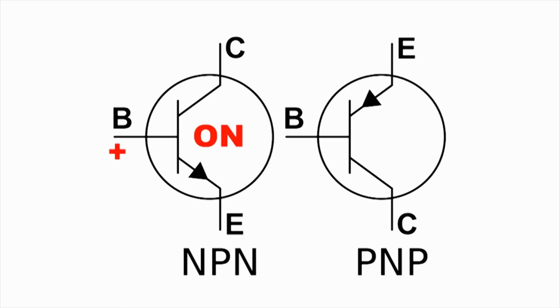Well, transistors are available in both positive and negative polarities, and that's where we get the NPN and the PNP. An NPN is kind of like a switch, which is normally open. It will not conduct until current is applied to the base, and then technically it's on. PNPs act in the opposite way. They actually reduce the flow in relation to the base current.